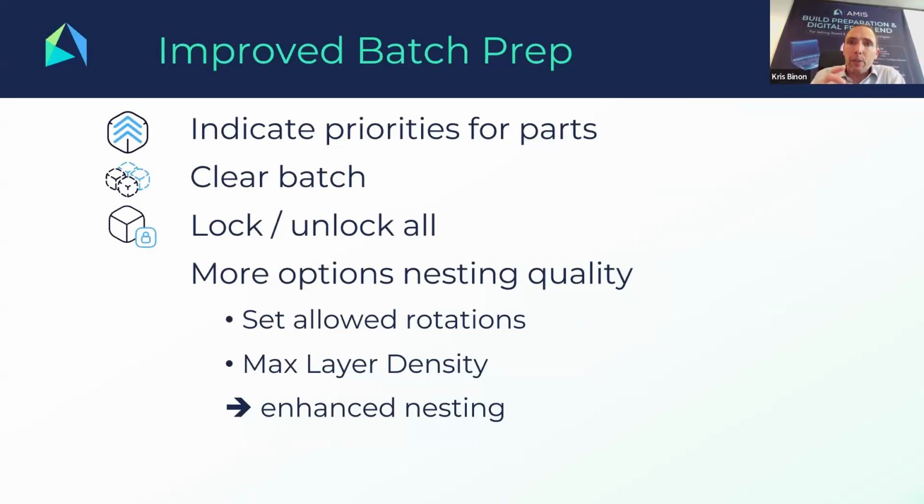Secondly, you can clear your batches. Also, that's one of those that doesn't look too big, but it's actually very useful once you start locking parts in place. Because if you start moving around parts and you lock them in position and then you nest, it's very difficult to get hold of that one locked part, which might be somewhere in the middle. So you just throw out all the other parts again, leaving only the locked part, so that you can more easily manipulate that. So it's just a very easy shortcut.